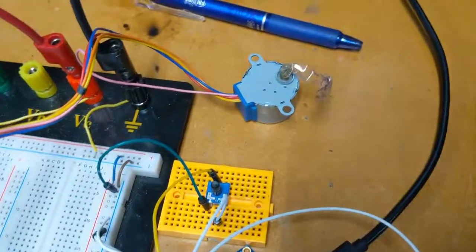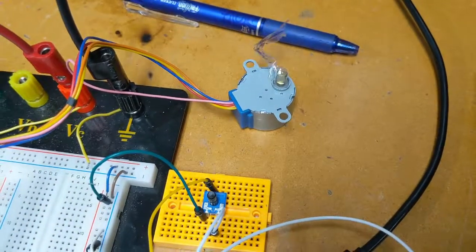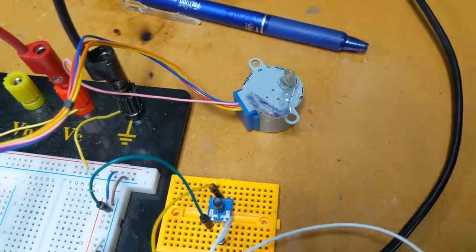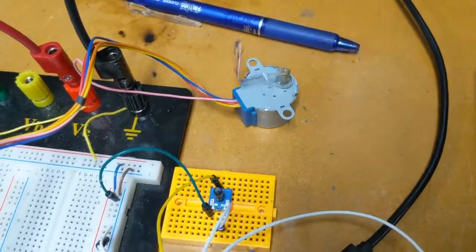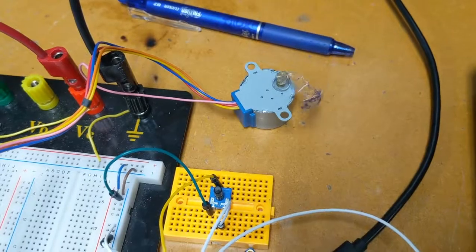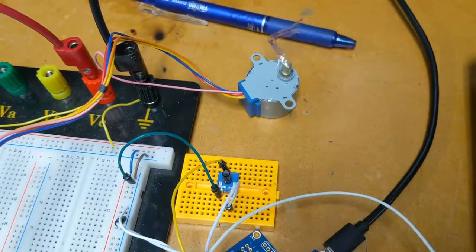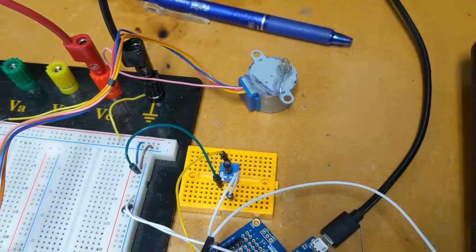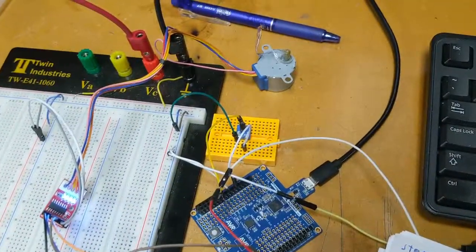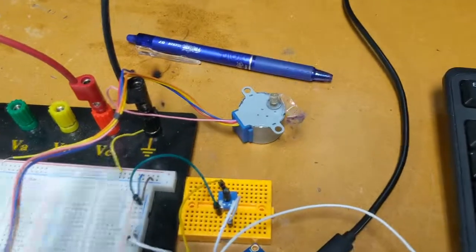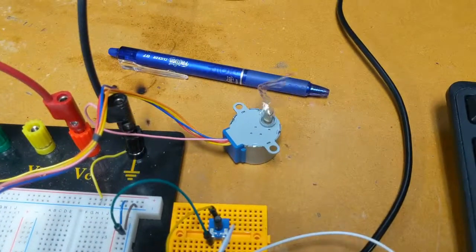You see there's actually been a time or delay it took to be able to go in and actually take an ADC value. So the interrupt is occurring in between, between reading and stuff like that, to make sure you get a correct measurement out. So you have a little bit of play in there that goes on. Of course, some of that is clock cycles to get completed, which is pretty good. But either way, you got a little bit of delay in there to get that measurement done correctly.